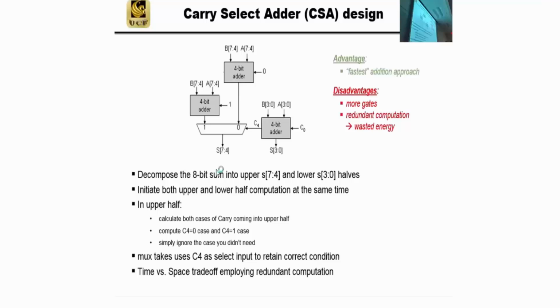How many bits are inside T3? 32 bits, because this is a register in MIPS. Take the lower 4 bits as A. This is A, where's B? A is T3, so what's B? Okay, this is A, so here's B. You can do A, B or B, A, right? It's commutative. So this is the lower 4 bits of one register and the lower 4 bits of another register. We add them together, we either get a carry or we don't.